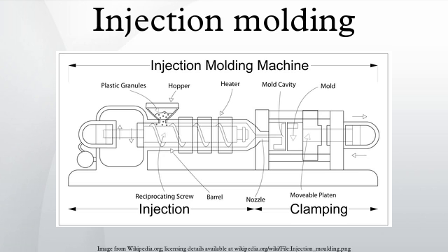form the desired part. The amount of resin required to fill the sprue, runner and cavities of a mold is a shot. Trapped air in the mold can escape through air vents that are ground into the parting line of the mold, or around ejector pins and slides that are slightly smaller than the holes retaining them. If the trapped air is not allowed to escape, it is compressed by the pressure of the incoming material and squeezed into the corners of the cavity, where it prevents filling and can also cause other defects. The air can even become so compressed that it ignites and burns the surrounding plastic material.